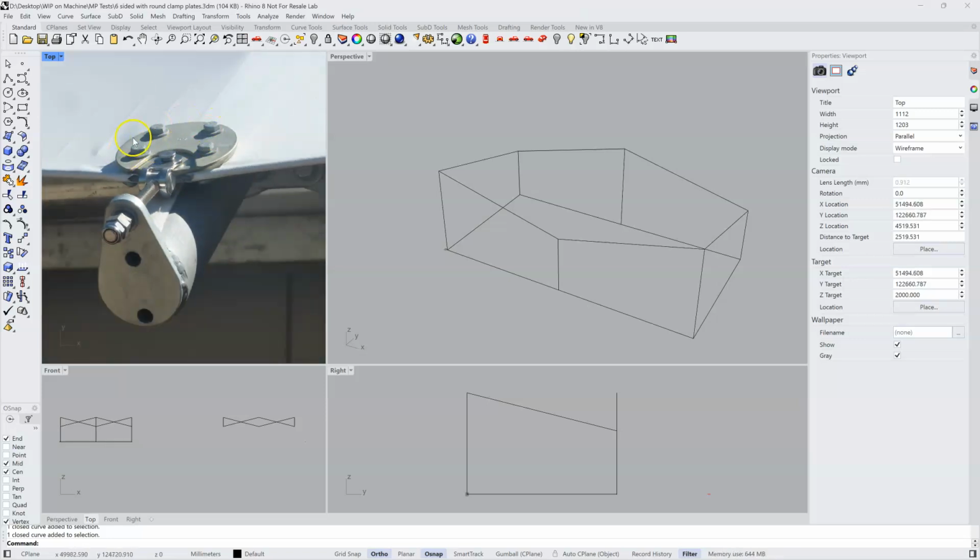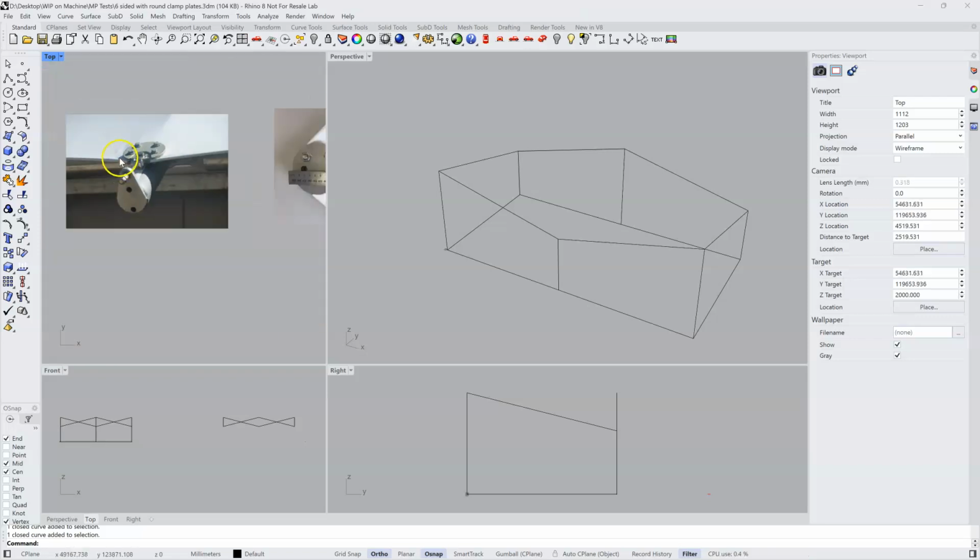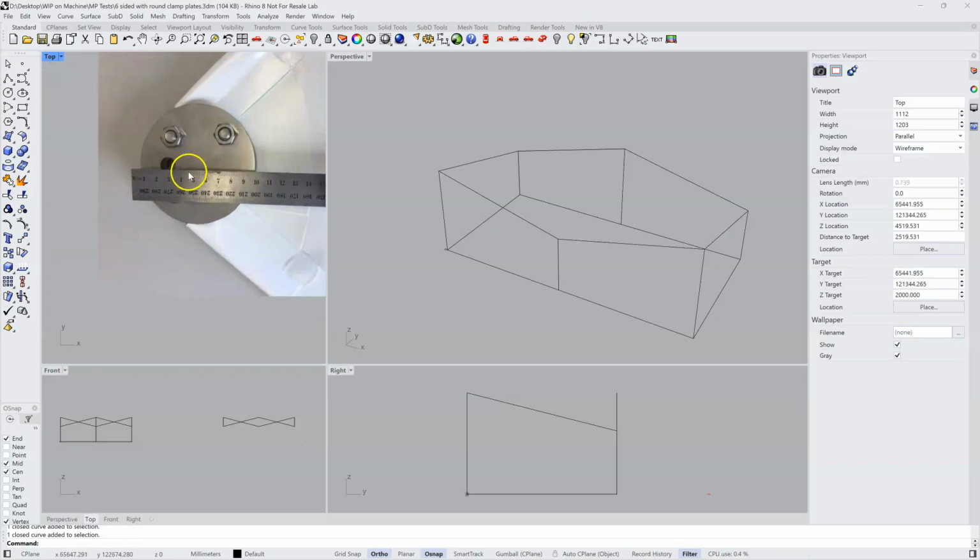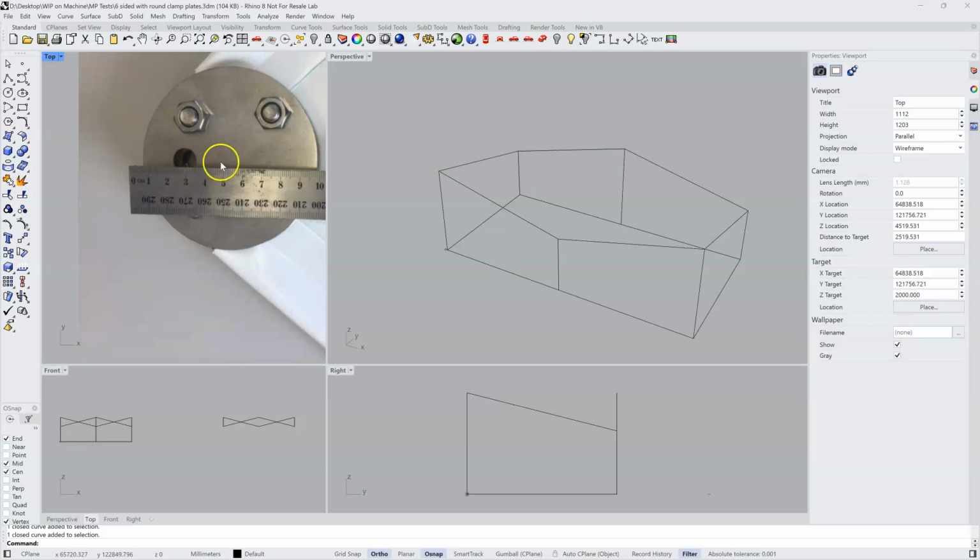And we can see we've got 4 bolts and a connection point to the clamp plate. We need to know the distance from the center of the clamp plate to the actual tensioning hole. In MPanel we will work to the center of this clamp plate.